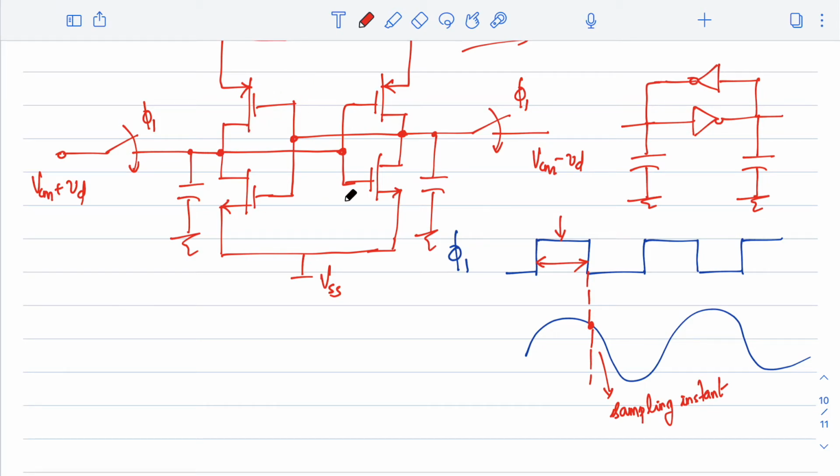If the inverters keep on operating, so I say initially during phi 1, some voltage is coming. Now the inverter started regenerating. So how is it regenerating? It is actually regenerating in the same node itself. So now I don't think the data can be properly coupled to the capacitors if we are allowing the inverters to regenerate during the entire time of phi 1. Do you agree to that? Yes.